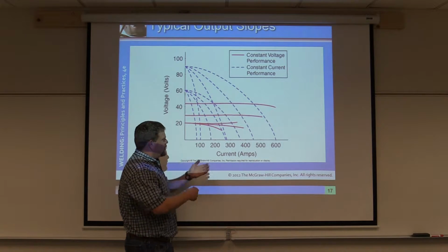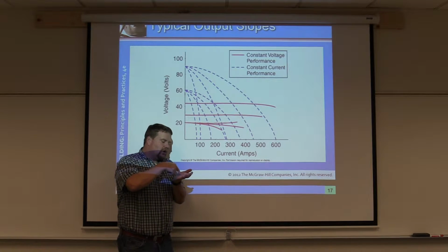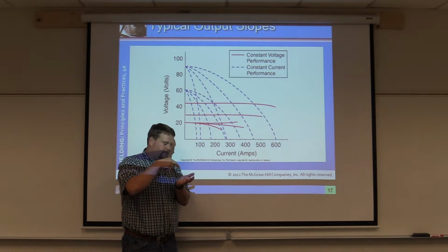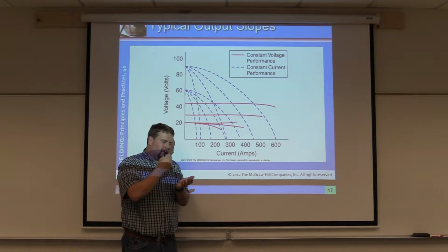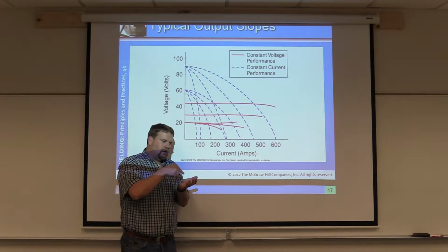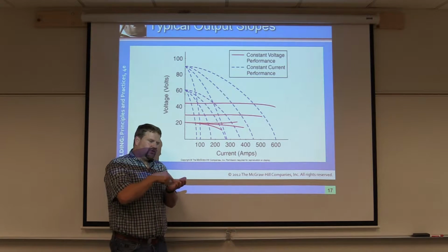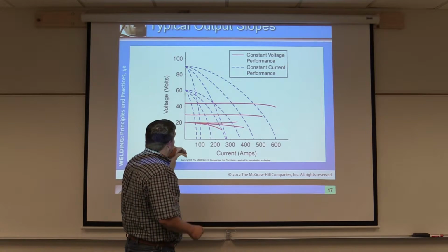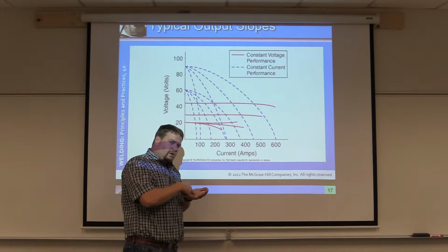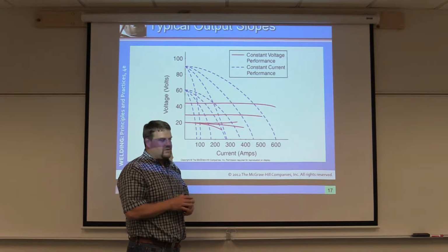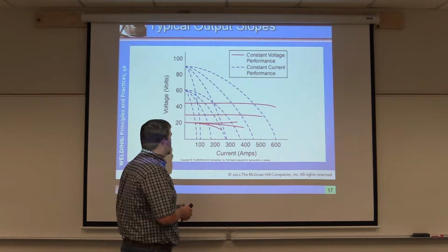And this is usually the point in wire welding when the wire starts to hesitate, pull, stutter, okay? So, at that point, we need to bring it back in a little closer, or possibly turn our wire speed up and voltage as well. Again, essential variables. Things can change drastically.